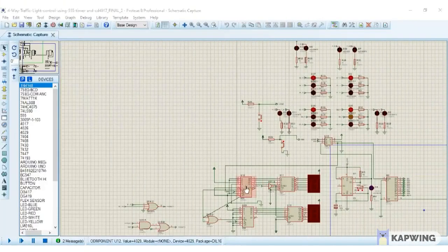Now we will see the display part. Here for controlling the 4029 decade counters, we have implemented 2 logic circuits. And the outputs of these counters are termed as preset 1 and preset 2. The upper and lower 7-segment displays are for unit and decade points respectively. Now we are going to run this project.